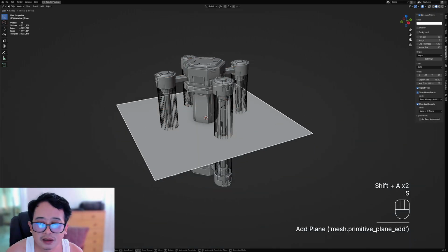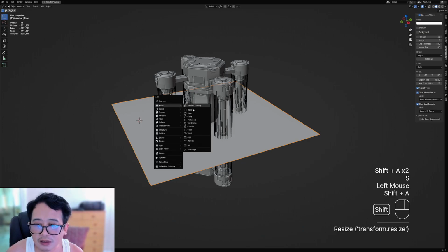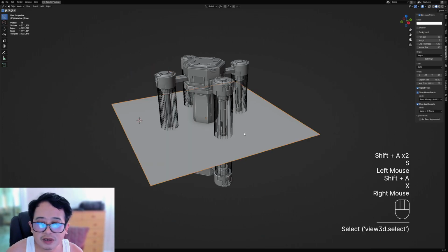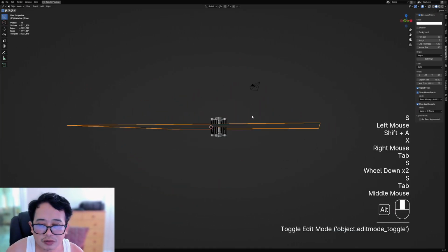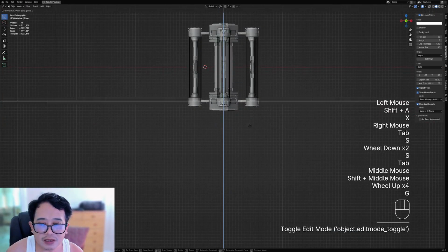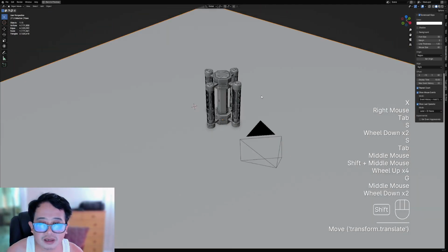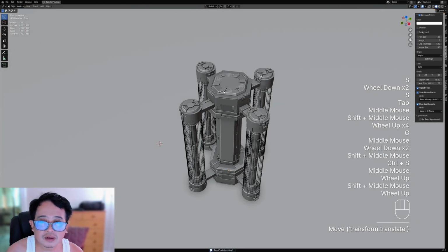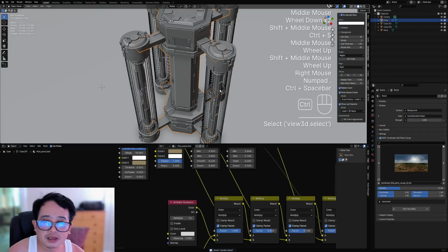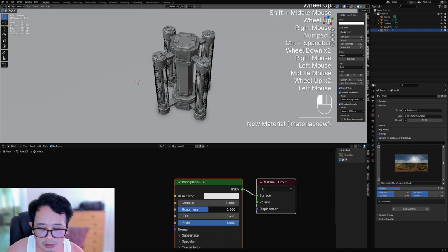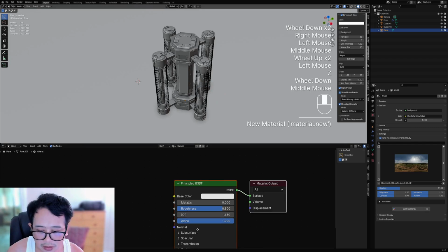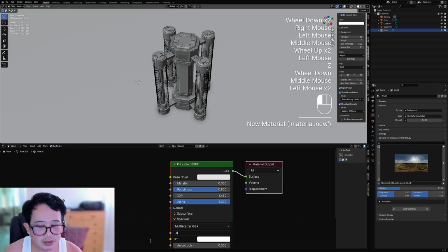So like that, if you click on there, you can use that to your advantage to accurately place stuff, even stuff like bones for your character, especially with the fingers, the hand, and this one new. So roughness 8, specular 0.05.